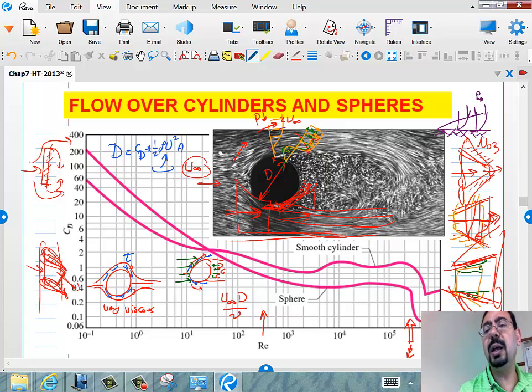I can make the area drop 10 times in a nozzle. I can make the velocity speed up like crazy and the pressure drop like crazy. But I cannot make the reverse on a diffuser. Meaning, I can send the flow into a small diffuser, small angle, but if I try to make the diffuser bigger, the flow will not go through. It will separate.